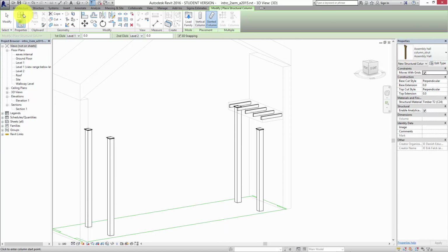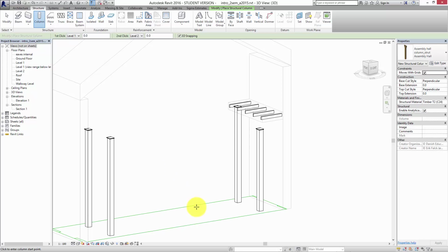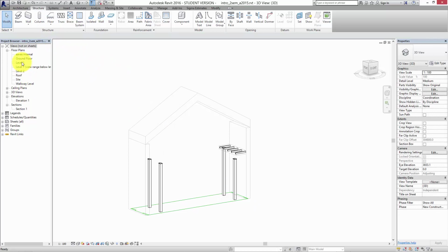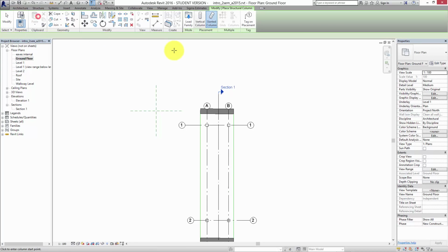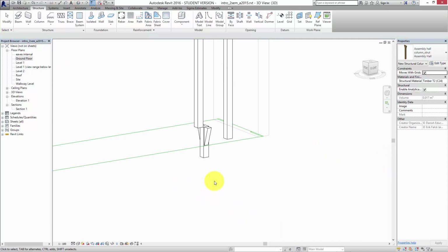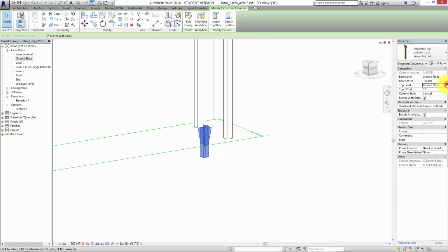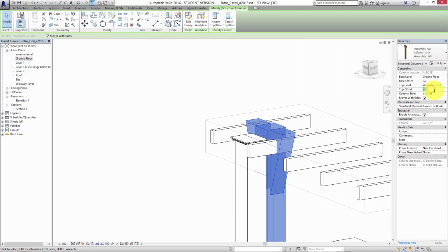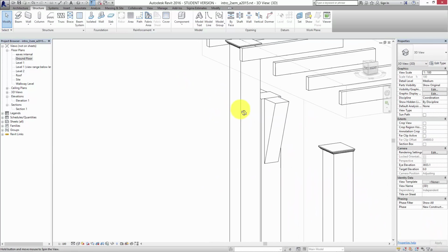And it turns up over here, and we can use the structure tool to add a column, and we want to make sure it's not a, let's just go into the ground floor to do it correctly. So column, make sure it's a vertical column, and we can put it in somewhere like that, isn't it? Just slightly behind the other one. As usual, when you put a column into Revit, it appears slightly below ground level, so we need to go and modify it once we get in there. So it goes ground floor to, let's say, walkway level, and we take off the offset. Apply. So then you got 2 columns in there. And then, of course, you can play with the offset from the top back to whatever you want it to be, so that it works with however you've got it set up. Okay?